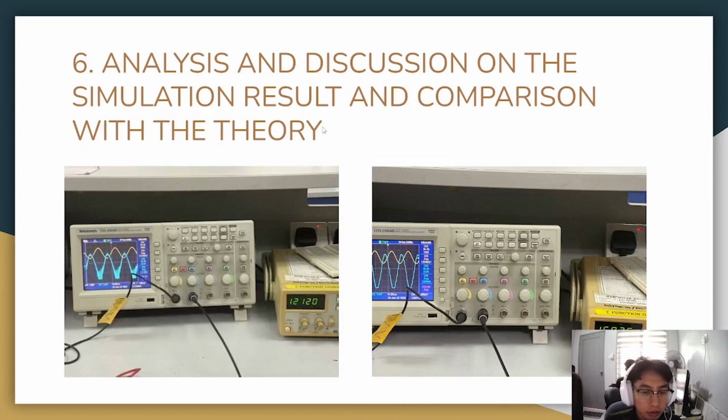Okay, so this is the proof that we tested the component at the lab, and this is our first try. We got this frequency response, and this is when FL is 1.5 kHz. The frequency is 1.5 kilohertz, and we get Vin of 1.02 volt, and the Vout is around 35.6 volt.